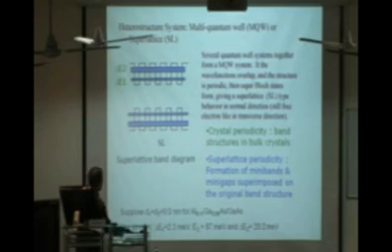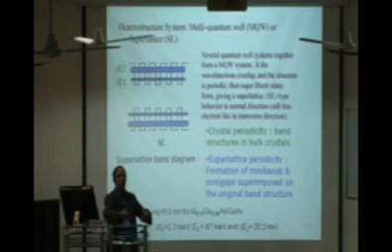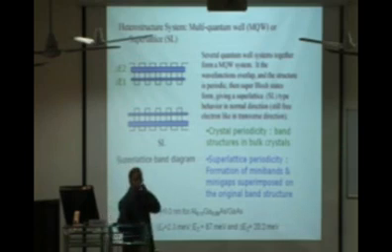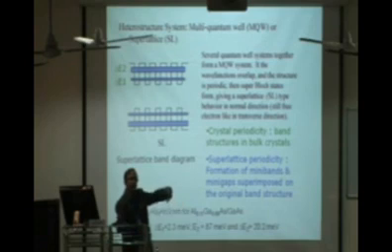We get an energy separation, where E1 is the ground state energy level and E2 is the first excited state, and as you see the energy difference is about 60 millielectron volt, which is much more than the room temperature energy of about 26 millielectron volt. So you can get 3 times that energy. That means you can make a superlattice. You can have superlattice transport in a semiconductor which works at room temperature and which can give you lasers.